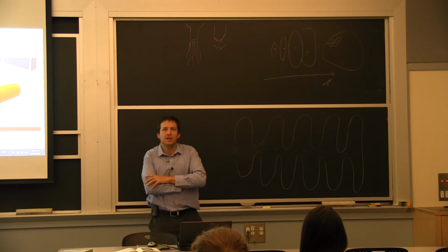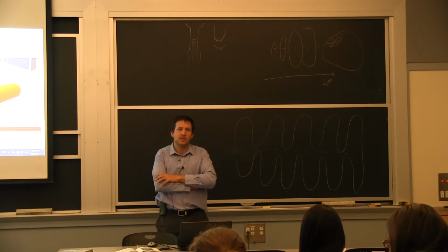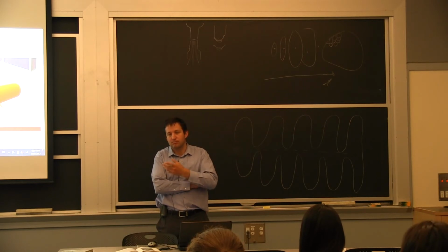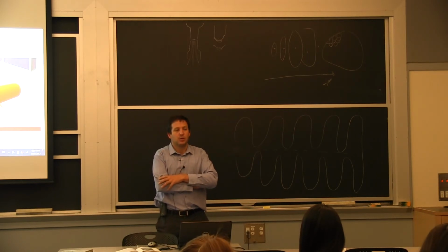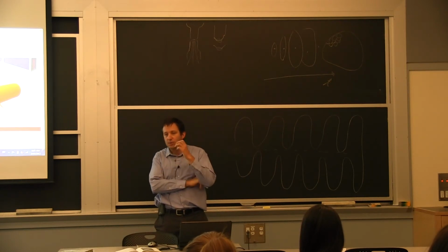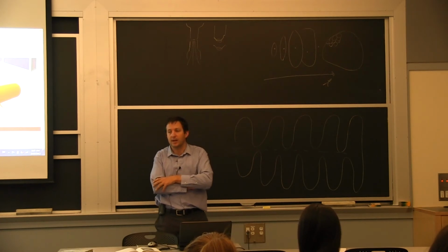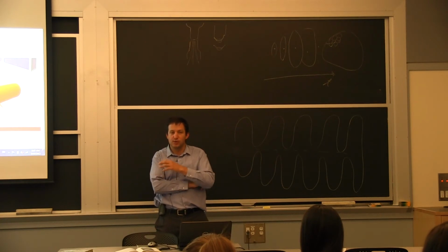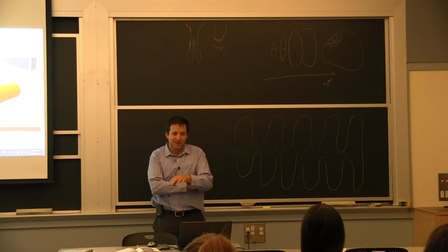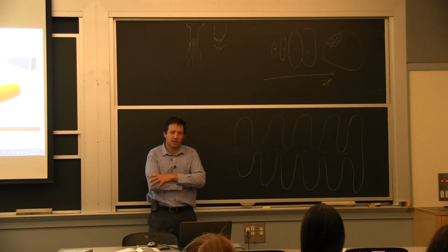Polyethylene is unique in the sense, as opposed to PVC, it needs antioxidants in its base formula to resist oxidation. So depending how much you expect oxidation in service, you have to include more or less of that antioxidant package. It's a little bit like red wine. It's going to be really good, really good, really good, until all of a sudden it goes bad. And that's what we were saying with that system.